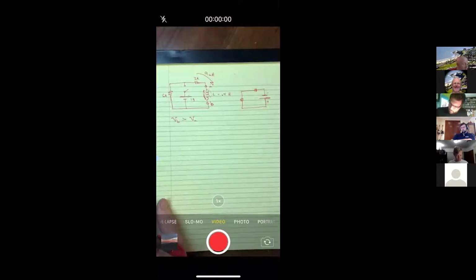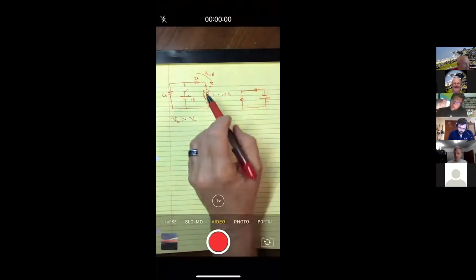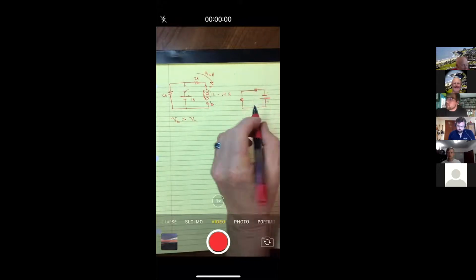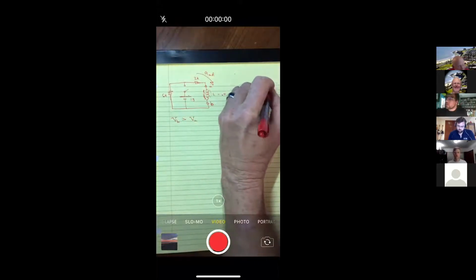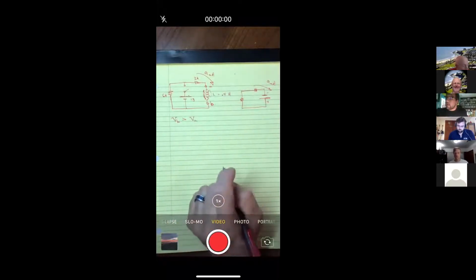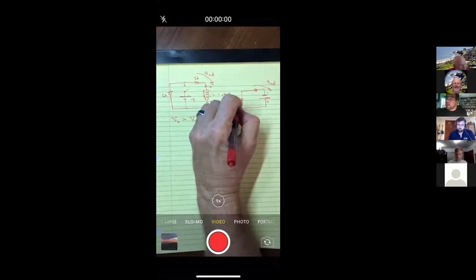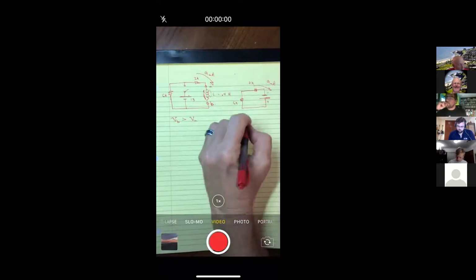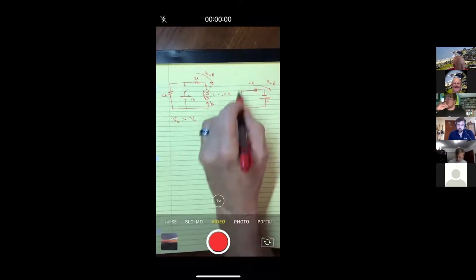Okay. So that would kind of be my argument of, okay, how do I know which one has a greater potential? Now, the other thing I would do is say, okay, to get that voltage, and in my mind, I'm just going to think of this as a momentary power supply. Of course, it's going to change, but at that moment, I've got to keep this current of 9 milliamps flowing through this inductor. So if this over here is a 6K and this is a 2K, those two together are the equivalent, because they're in series, of an 8K.